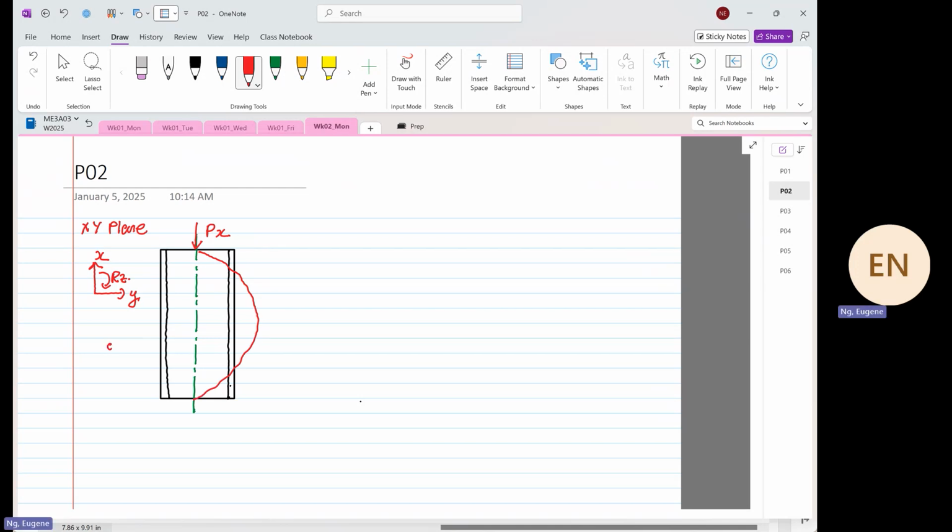So now we know over here, this is your RZ, right? You draw the circle because of the rotation. So we know that based on the curvature, and the curvature over here is the same, our critical load becomes pi squared E multiplied by IZZ over L squared.